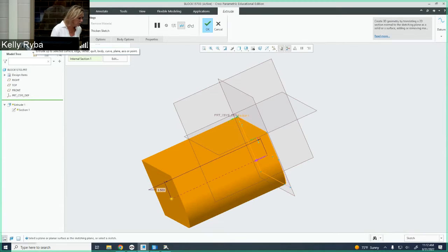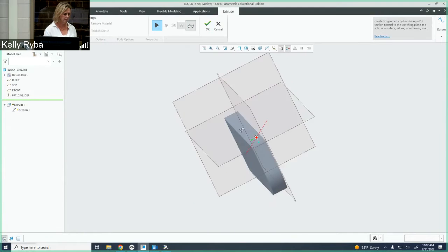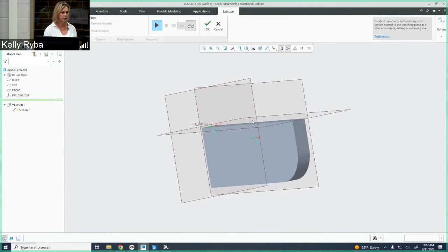So we're going to do just the regular depth here, and we're going to put in what we call a blind depth. Our blind depth, it doesn't give us the thickness in this example. Again, it's kind of an informal tutorial demonstration. We're going to give it a 1/2 inch and then enter. So it should automatically do it for us. Now, before we officially say okay, Creo asks, do you want to look at it? So these little glasses here are like a preview of what the final part is going to look like before we officially hit the OK.